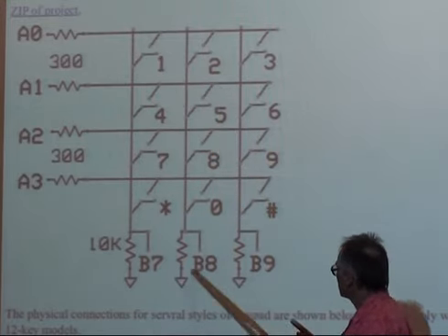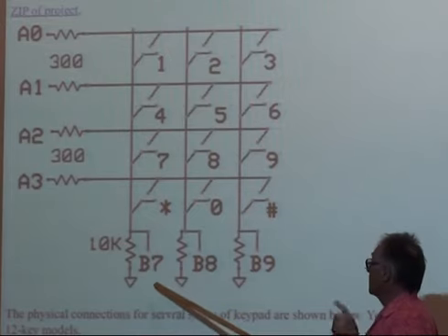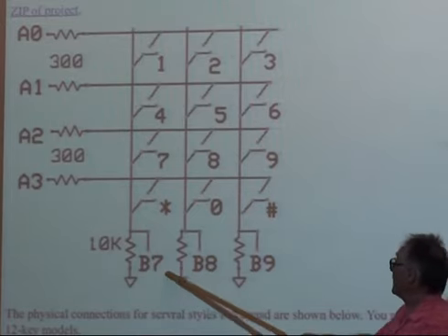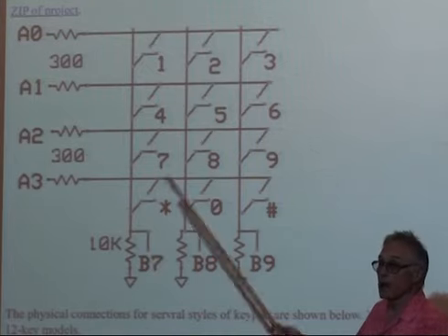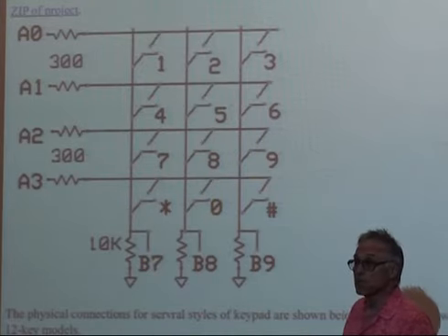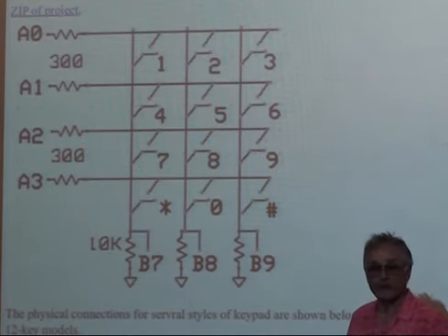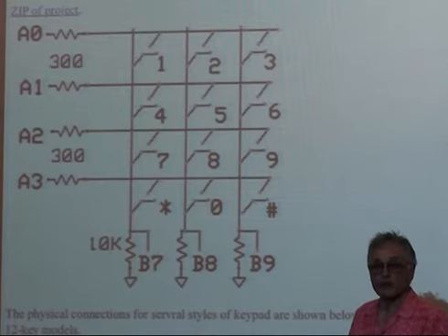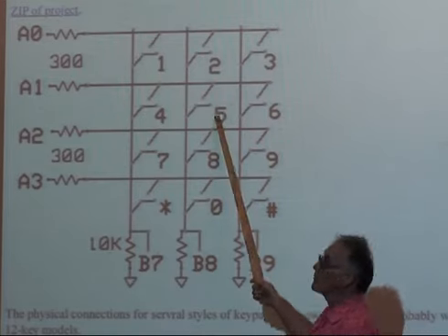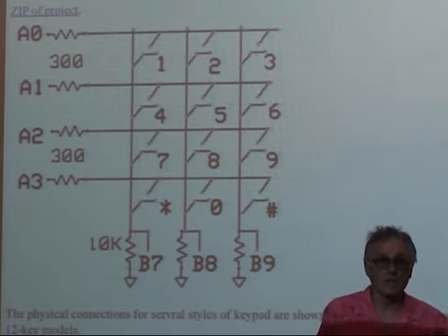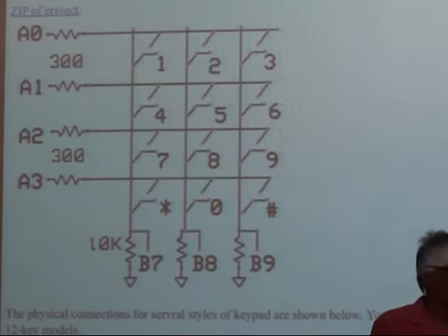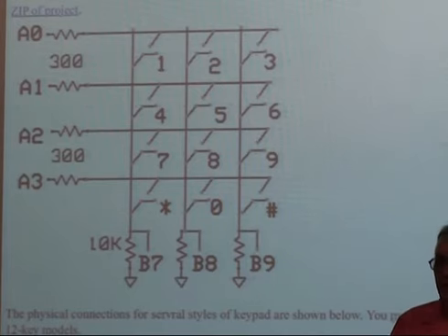And the scan code will be 7 and 8, so that's hexadecimal 181, which isn't in the table. And so you will return a -1. So if you press 2 keys in the same row, you get a -1 saying that there is no valid key push. So -1 can mean either no key push or no valid key push.